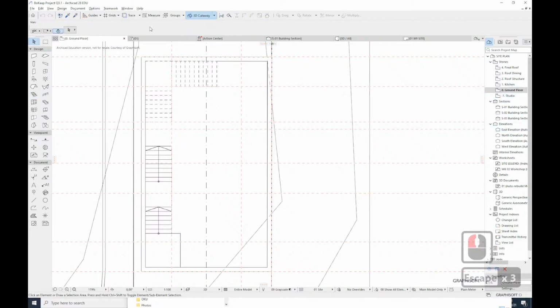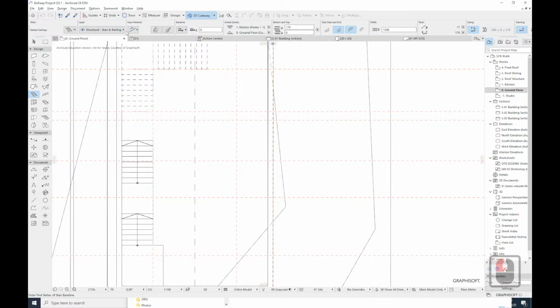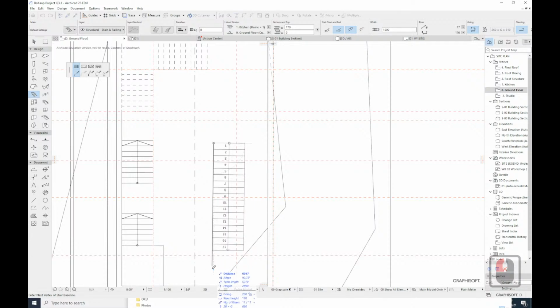Levels. Is it kitchen? Yeah. So they are all in the right order. Okay, great. So ground to kitchen. All you need to understand is when you create a stair, you must tell it, I only want you to go from ground. You see where it says home? That's your home story and that's linked to there. Now you just start drawing. Then this is only linked to those levels. That's the maximum stair. Yeah.